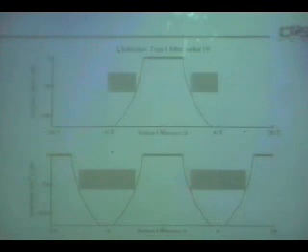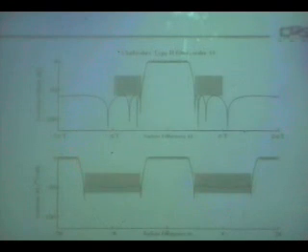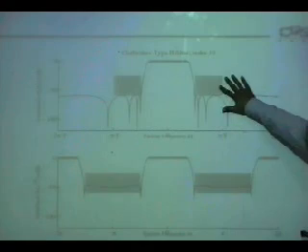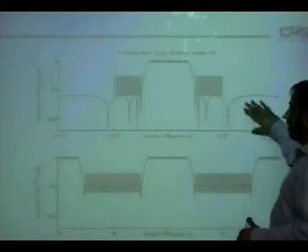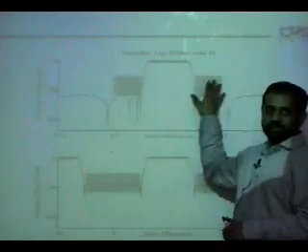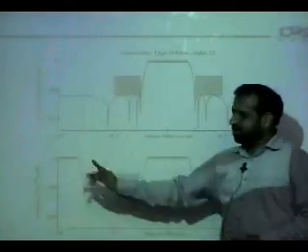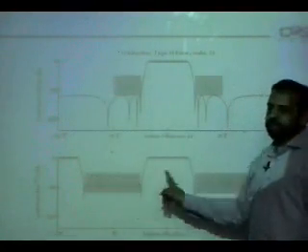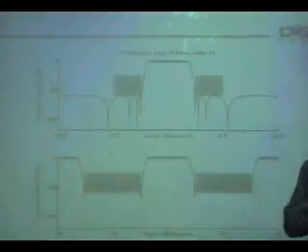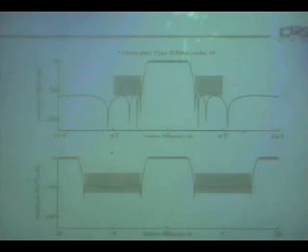But on the other hand, if you use Chebyshev type 1, you may be okay, because it is smoother here. But this is for type 2. This meets specifications. Ripples here meet specifications. Once you make copies, the discrete no longer meets specifications because of the aliasing effect.